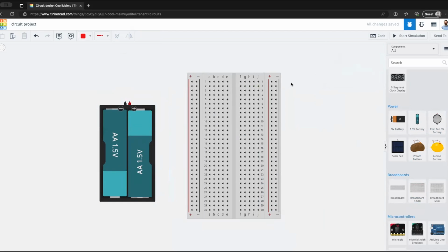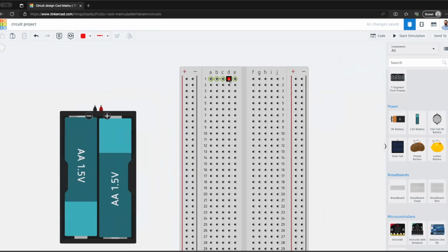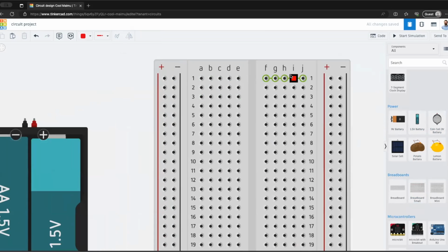And as I've taught breadboarding, I have found that my students often struggle to learn how to use it. And the reason is there's a lot of holes, right? There's a lot of places. It's very easy to accidentally put something in the wrong location so that your circuit's not connected. I love that in Tinkercad, when you hover over this, it shows you how the breadboard is interconnected. So for example, every space here in this first row, columns A through E, are connected to one another.